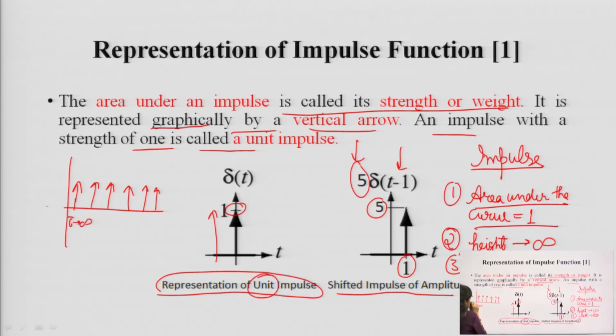So, this is known as the train of impulse function, and you have to multiply this train of impulses with the input signal, so that the operation is performed as a convolution and you can modulate the signal. It can be written as summation over k from minus infinity to infinity of p(t minus kT), and capital T is nothing but the sampling time.